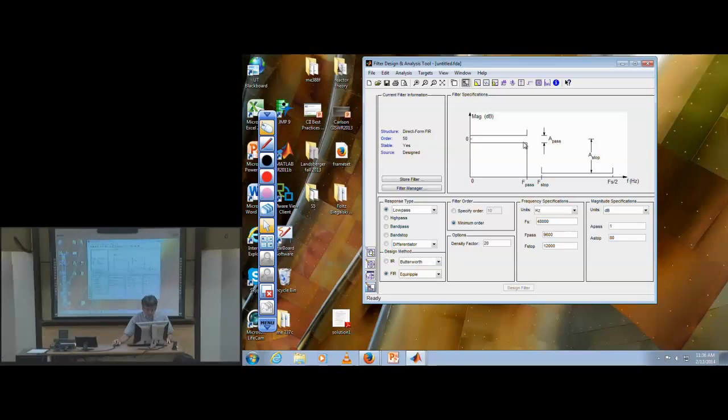All right, so I asked you to do equal ripple, which is another name for Parks-McClellan, Remez exchange, lots of different names for the same thing. So the minimum order, let's see what I need. I need low pass. Can you pass parameters into this? Oh, I'm going to do the example that we're going to do in class. So in homework, it's a bandpass example. Can you pass the parameters into this not using the GUI? Correct. There are command line interfaces too, but it's not as clean as this. You're going to have to go dig in finding the right MATLAB command. You don't want to use the graphical user interface.